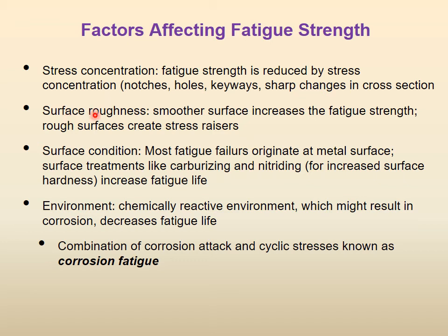Surface roughness, another factor. A smooth surface increases the fatigue strength. If the surface is smooth, the material has high fatigue strength. But if the surface is rough, roughness means stress concentration, but this is a stress concentration only at the surface. So surface roughness will again reduce the fatigue strength of the material. Other surface condition: most fatigue failures originate at the metal surface.